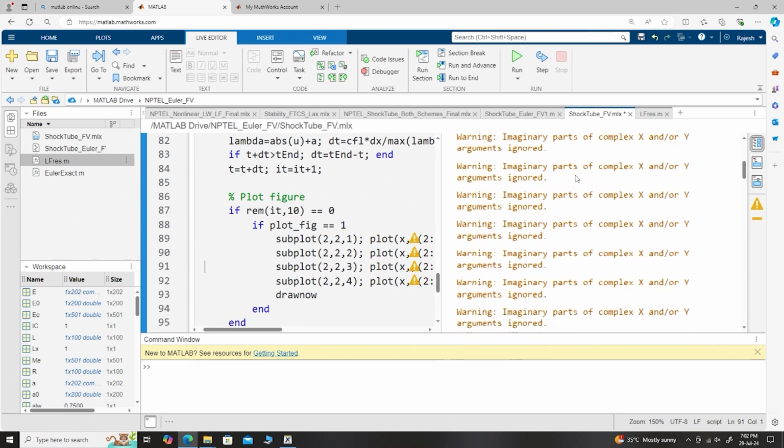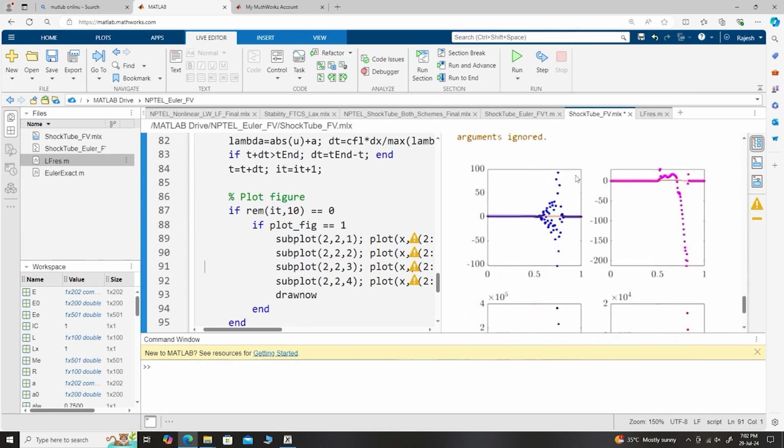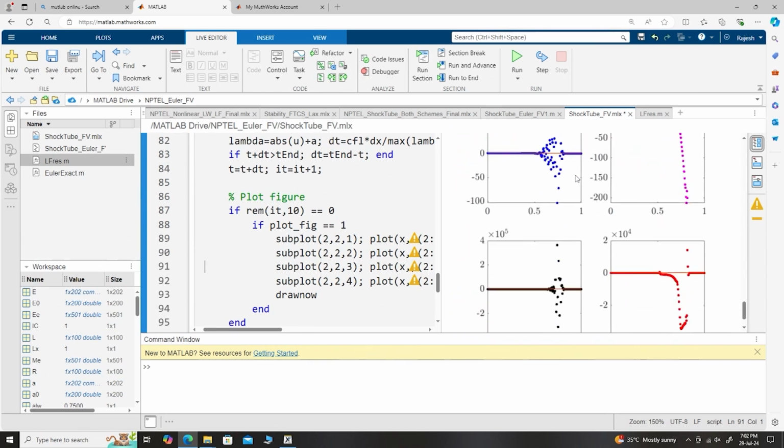So, that is why the limiter is very important in finite volume coding. Okay, although it is a very small part, you have to make sure that you are not overshooting or undershooting the maxima, local maxima and local minima, right.